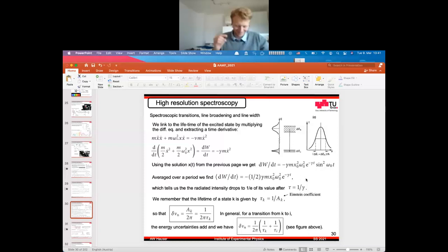So there is a certain series of steps that you're supposed to do in order to converge to the desired maximum output. And there are some tricks where you use certain reflections of the light and so on. So you have to know what you're doing in order to adjust the laser, and you get faster over time. So this is also a lot of experience that you need in setting up these tools.